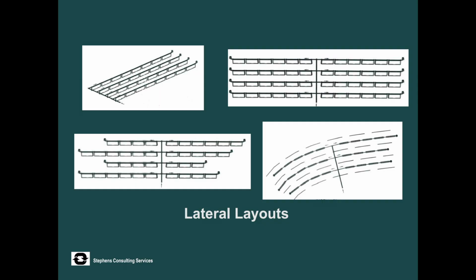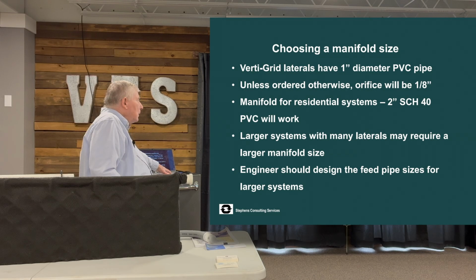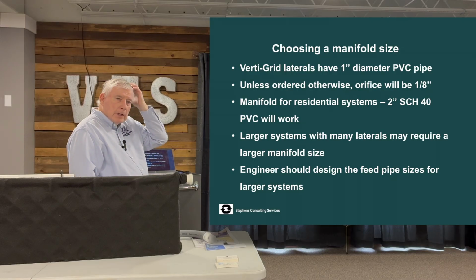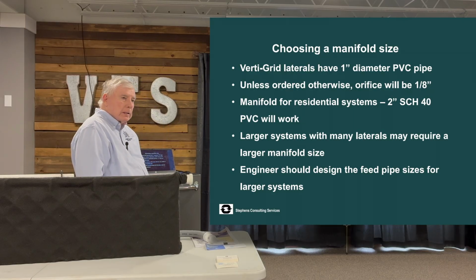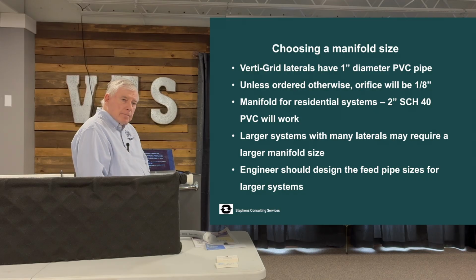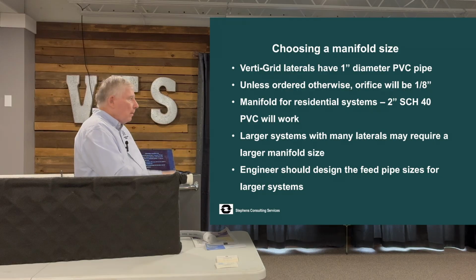Your imagination is the only thing limiting you in your use of these to work around other objects in the field. The tools are there. We kind of went through all of this. On larger systems, an engineer or somebody familiar with hydraulics should actually do a hydraulic analysis to size the manifolds and the feed pipe and the pumps.